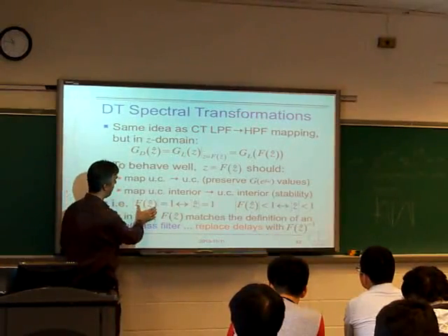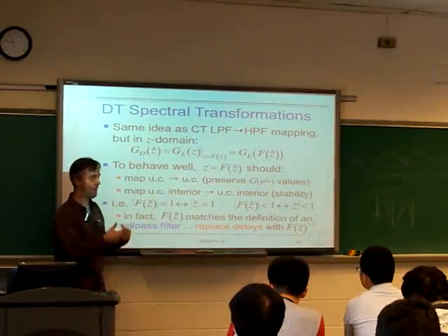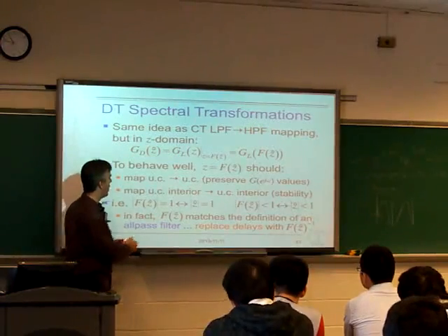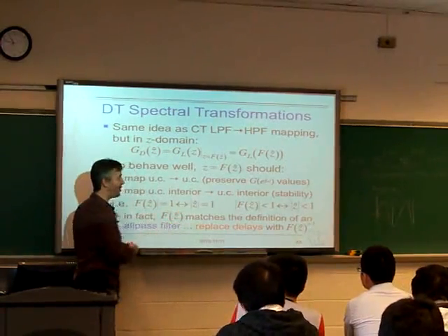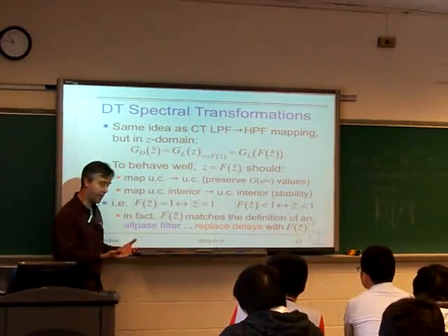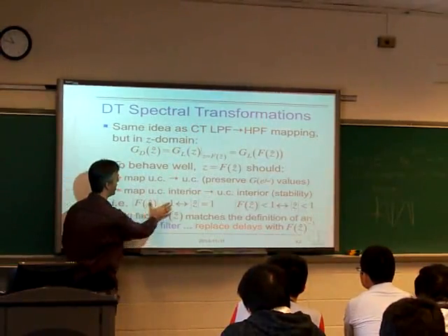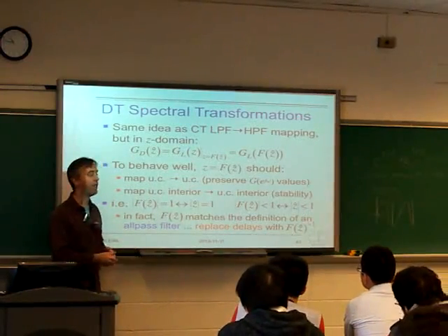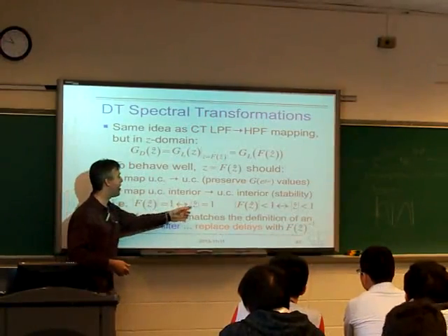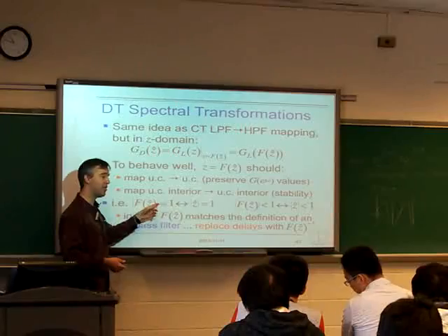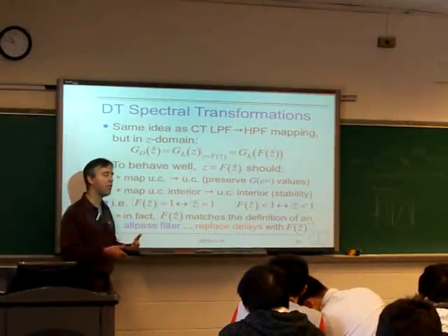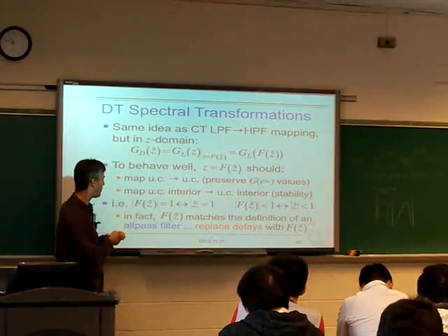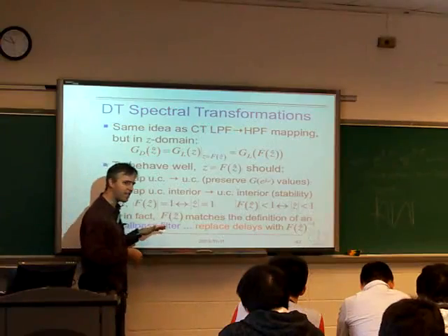If we just think of now, well, we've got some polynomial in z, which is like defining a system in the z domain, and we're specifying what its values should be for the unit circle, which is like specifying its magnitude response. And we're saying it should be constant, should be 1. But that would be an all-pass filter, a filter whose value on the unit circle always has a magnitude of 1. That means to say its Fourier transform, the gain that it would apply to any sinusoid would be 1. And so that's all we need.